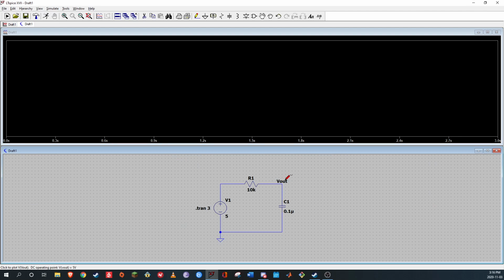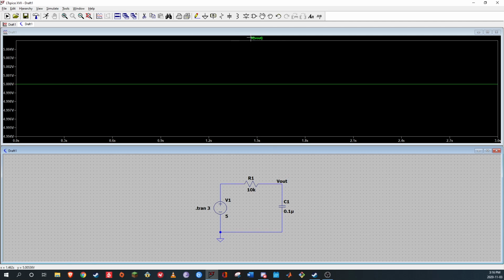And now you can specifically use Vout for measurements, and see, it'll even tell you that you're looking at your Vout net. And if I hold Alt and left click on Vout, it'll highlight everything that that net is taking into account. Since this circuit is really simple, that's a very easy node to look at. But once your circuits get a lot more complicated, if you have wires that are crossing, you just have a lot going on, it can be really helpful to highlight what net you're actually looking at and which components it's taking into account when it takes this measurement.